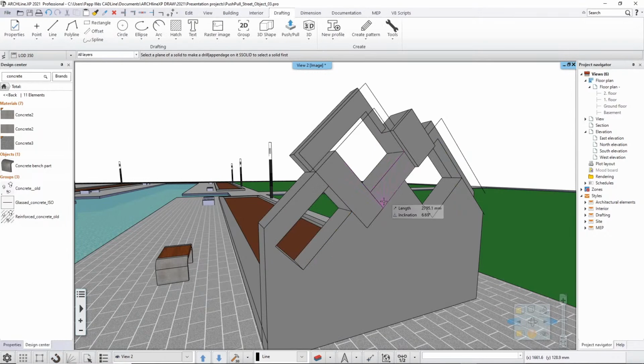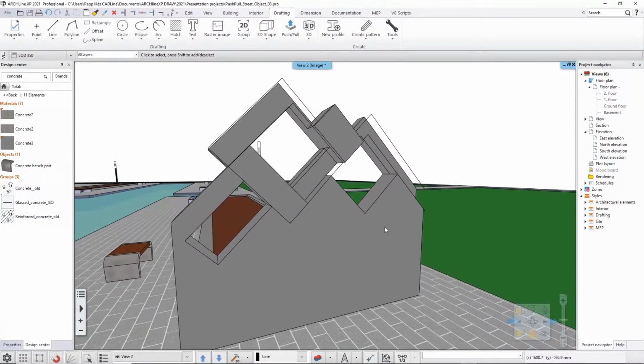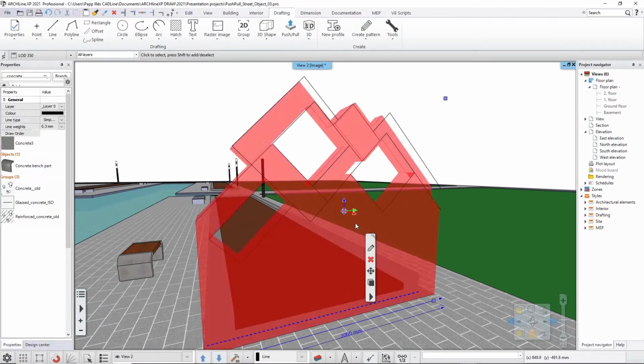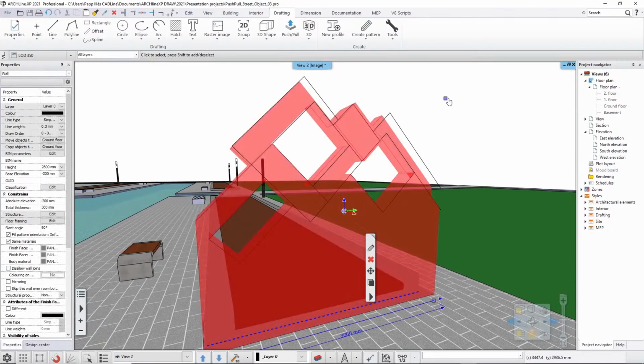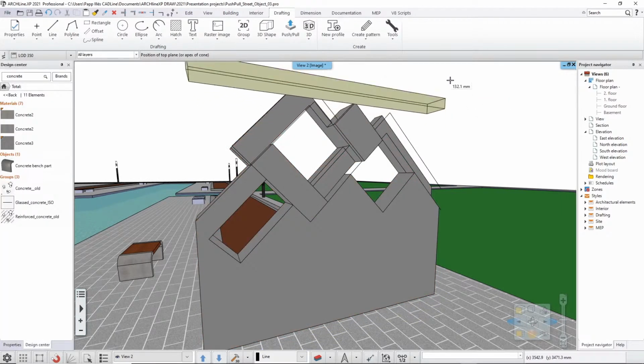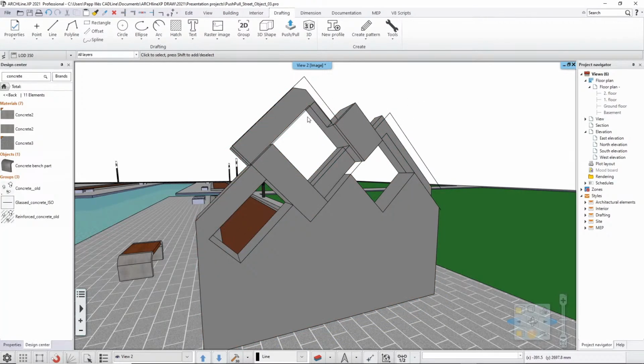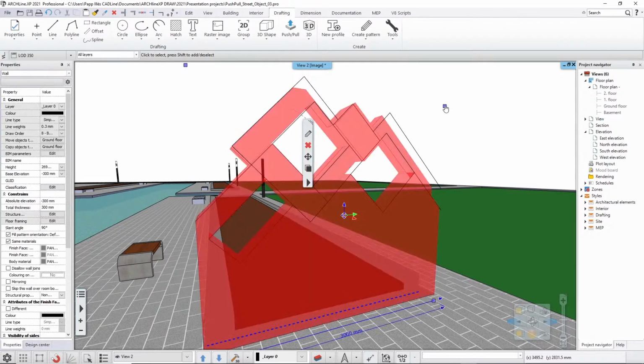And then the very good thing with this one is that once you have something like this, this is part of the wall. So what I have now is kind of a parametric extension of this wall. So whenever I change, for example, the height of this wall, because I would like to make it a little bit smaller or higher, see, the complete thing was kept, only the top was chopped off because I made the wall smaller than the original was.